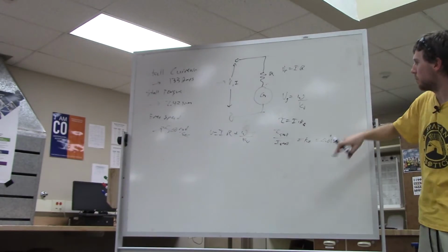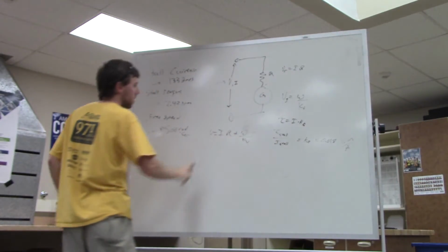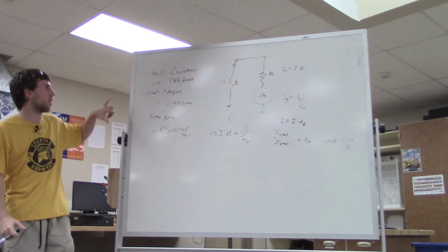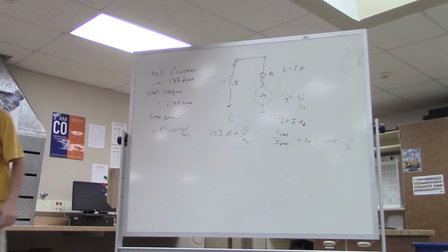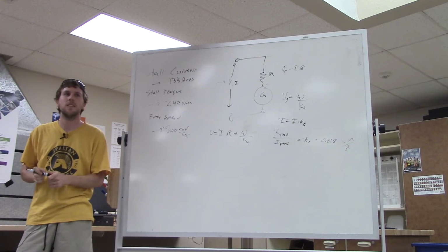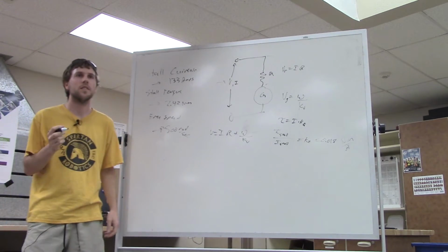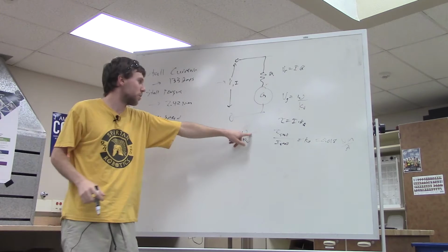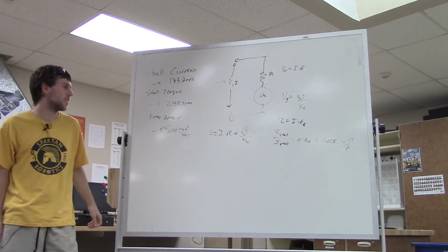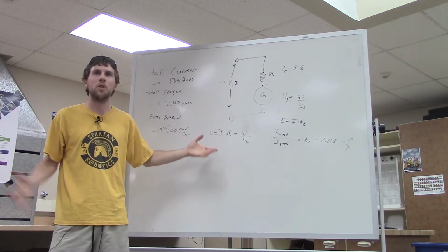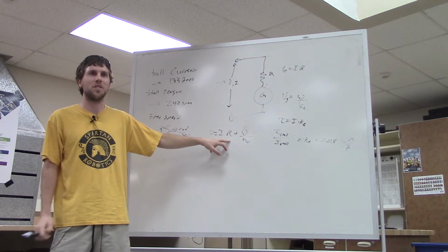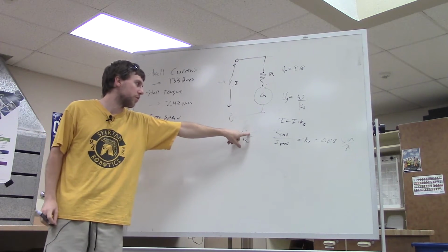Now let's do the same for this equation. I want to figure out KV. So how would we figure KV out from the same specs? Omega represents angular velocity. So you've got to use the free speed. Free speed would be at a 0 current? Yes. When the motor's spinning at full speed, we have no current. So 0 times resistance, doesn't matter what resistance is then. So this is 0. We've got free speed.